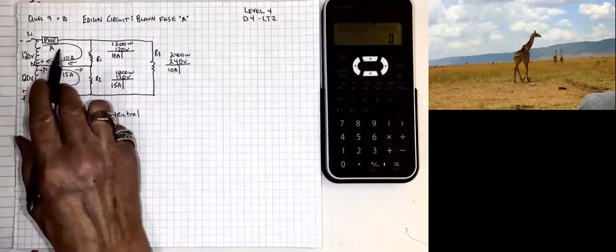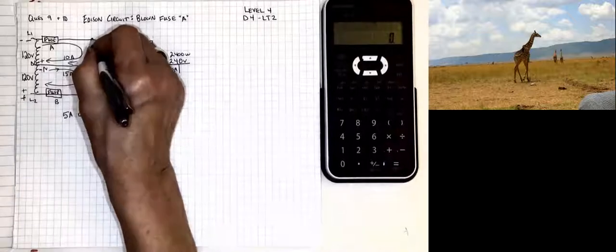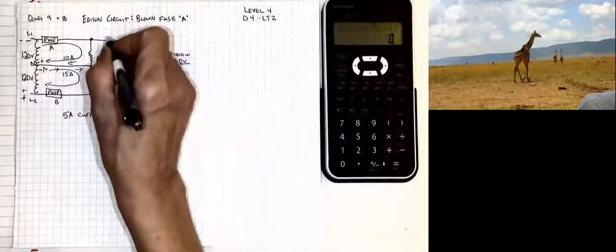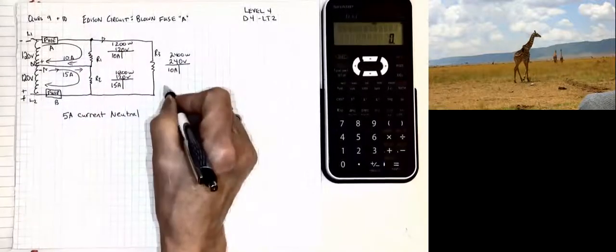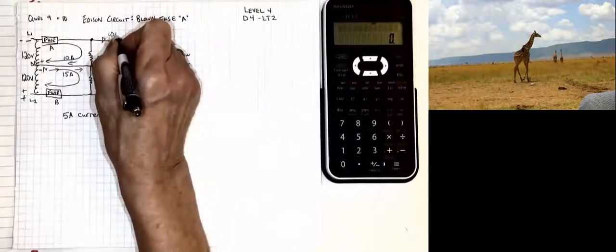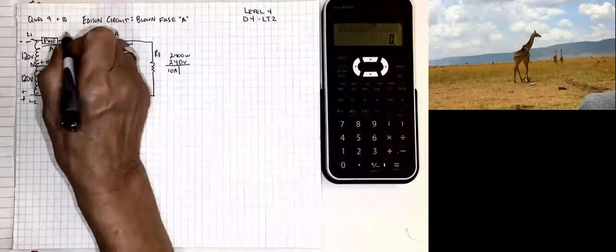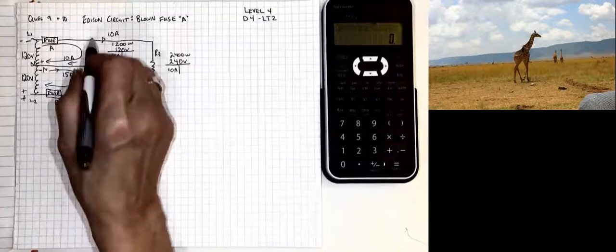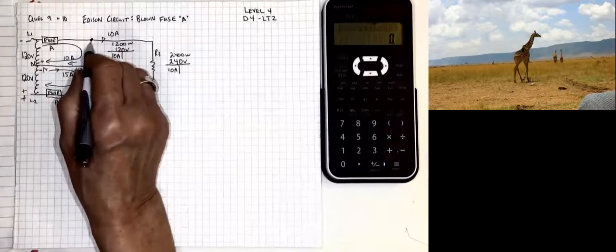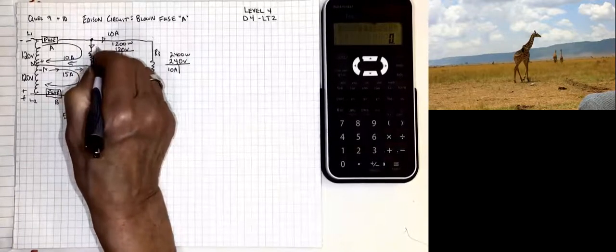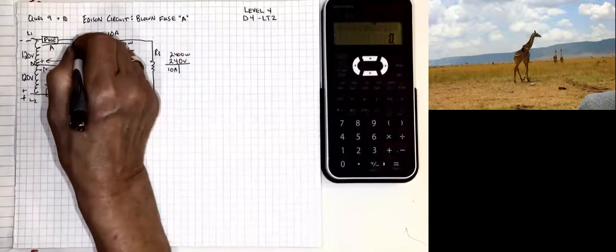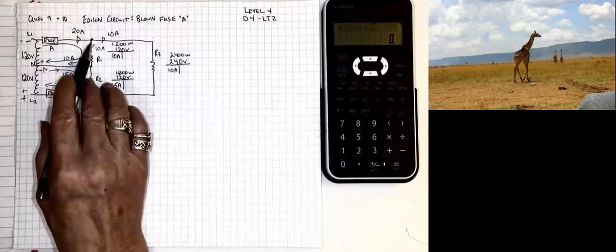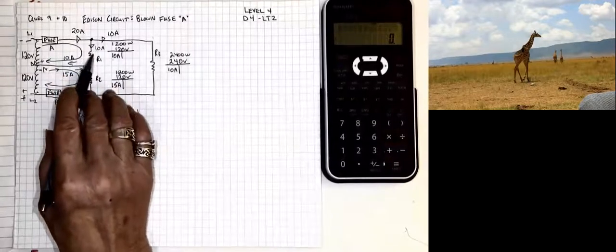The overall current, of course, would be a little bit different because we have to look at Kirchhoff's current law. If there's 10 amps flowing off to that load out here, and we had 10 amps flowing around because of this, then at this junction, we would have had 10 amps flowing down there, and at this point, we would have had 20 amps. So 20 amps flowing into the junction, 10 that way, 10 that way.